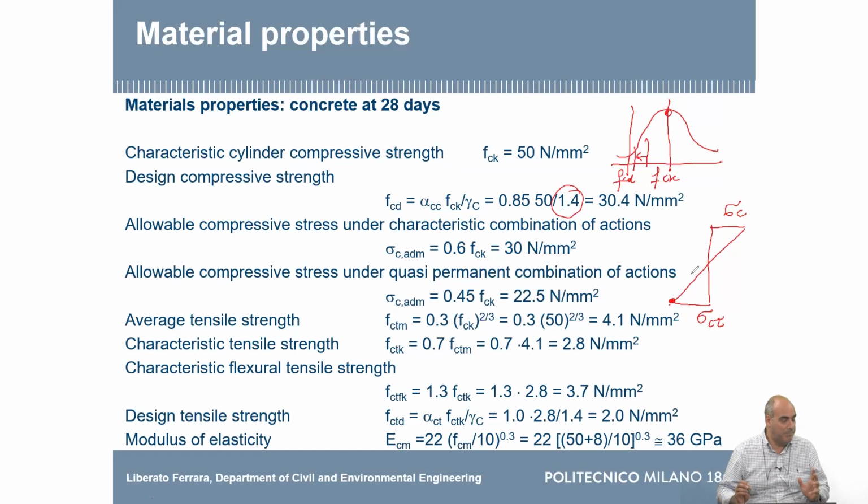And what happens is that in reality, when a beam really fails, think of an unreinforced beam, okay? When it really fails, it's not when you get here, but when you get to a distribution of stresses which is something like this. Because concrete softens after the peak, after the cracking, there is some life after.